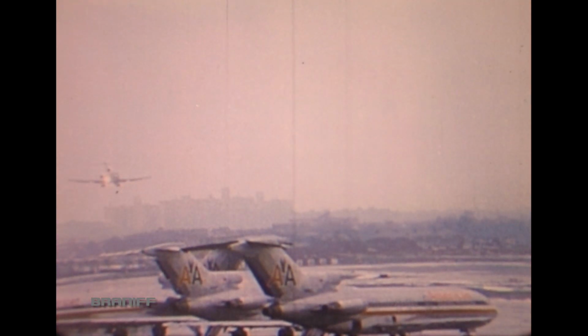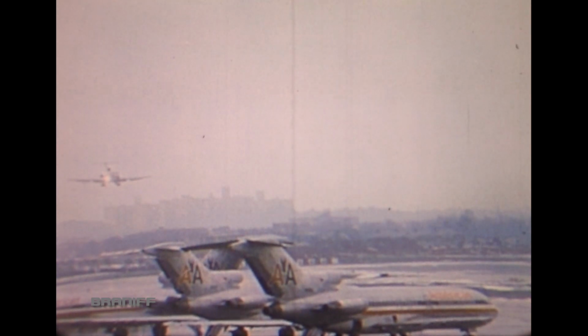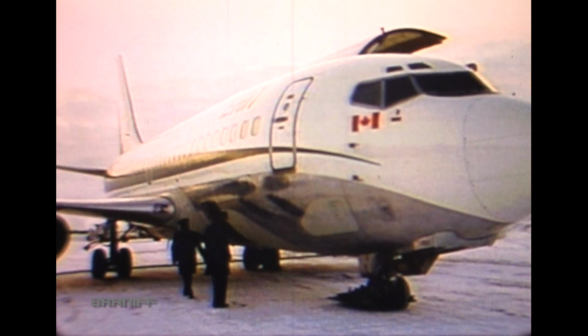In addition, ice or snow, or standing water on the ramps, taxiways, and runways may cause engine icing during ground operations. Let's see what actions the flight crew can take to minimize the effects of cold weather. An exterior safety inspection should be performed. This inspection will ensure that all ice, snow, or frost has been removed from the airplane. The guidelines used for this inspection are similar to those used during maintenance.